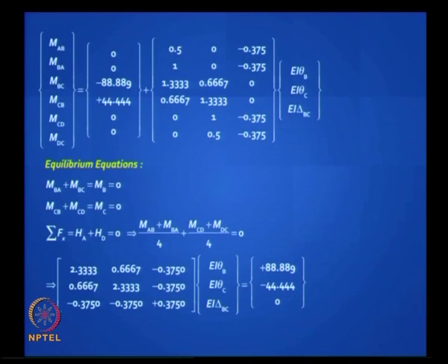beautiful part about this is the vector that you get here is caused by the loads. The left side is completely a property of the structure. You change the loads, only this will change, this will not change. And so we will see how you can generate that stiffness matrix from first principles. I am stepping ahead into matrix methods, but I want us to go through that exercise.